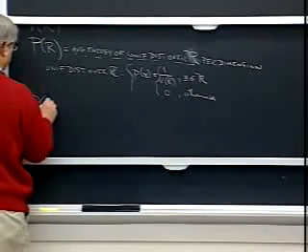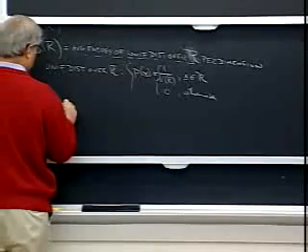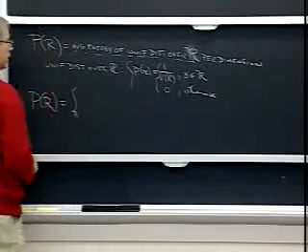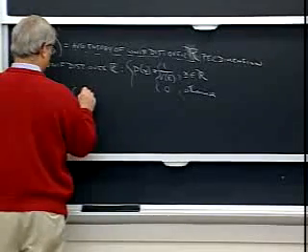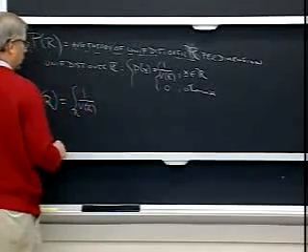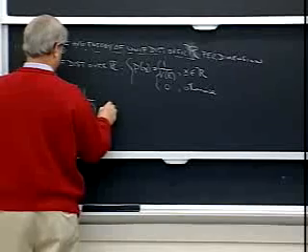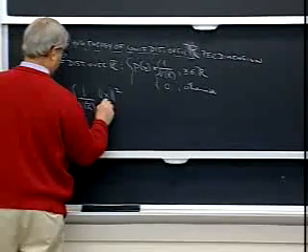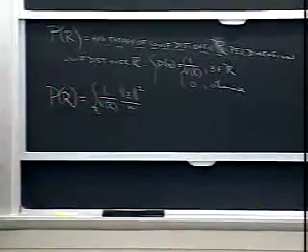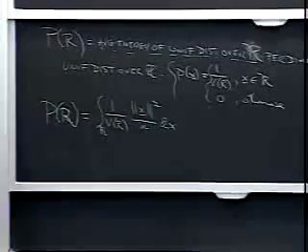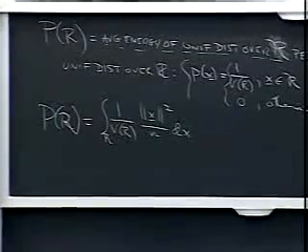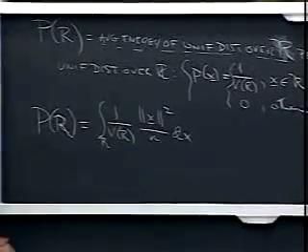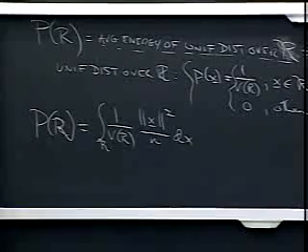So to compute P of R, we basically take the integral over R of this probability distribution, 1 over V of R, times what? The energy per dimension. The total energy of x is the squared L2 norm of x. Normalized per dimension, we're going to put an n over there, dx. Okay, so that's an equation for what it is I want to compute. I think it's much harder to remember the terms in this than to remember this verbal description of what we want.